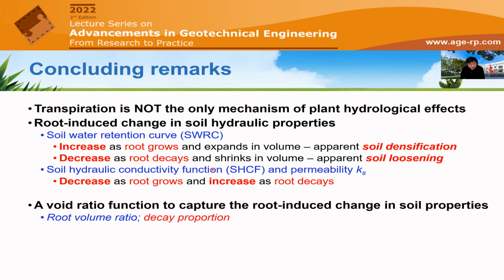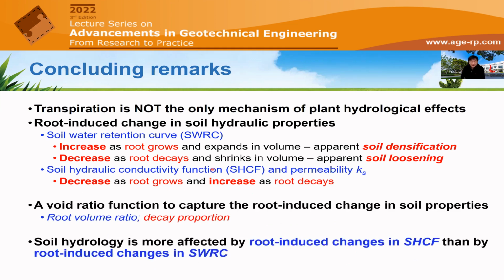And we have derived a new void ratio function to capture this root effect, purely considering physical effect, okay? And relatively speaking, the permeability function changed by the root is more significant than the case for the water retention. And that is exactly what we have been focusing on in our current research, looking in more detail at how the conductivity function is being affected by the roots more fundamentally.